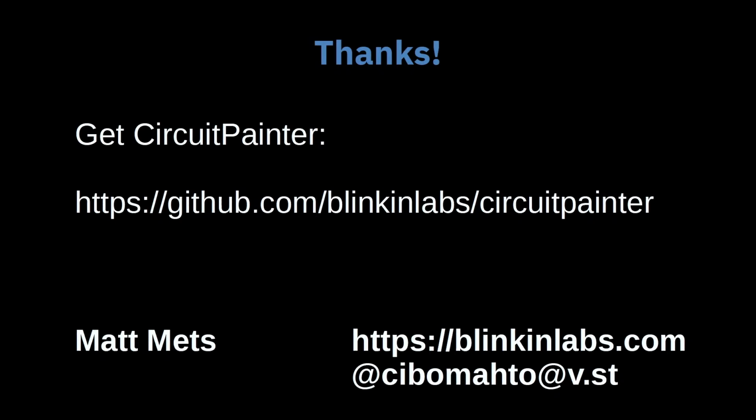So the question was, will the DRC complain because you don't have everything set up correctly, or the nets and things aren't? So right now, yes, it will complain. We're still trying to figure out how to do it more automatically, but what we could do is if you give Circuit Painter your schematic file, it could look through to try to reference which part is what, and then copy it in. The way KiCad does that, I think, is it has references in multiple places that say, on the schematic, this part has a name, but actually KiCad doesn't care about the name, it cares about the UUID for the part. So you have to figure out what the UUID is. But it's all there, and it's all in text, so you can figure it out. And of course, it's easy to script this.